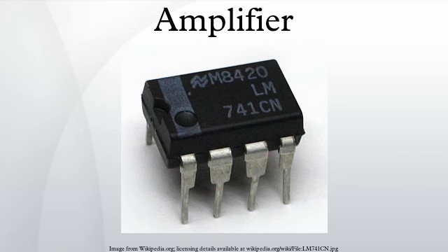The main challenge of the Doherty amplifier for digital transmission modes is in aligning the two stages and getting the Class C amplifier to turn on and off very quickly. Recently, Doherty amplifiers have found widespread use in cellular base station transmitters for GHz frequencies. Implementations for transmitters in mobile devices have also been demonstrated.